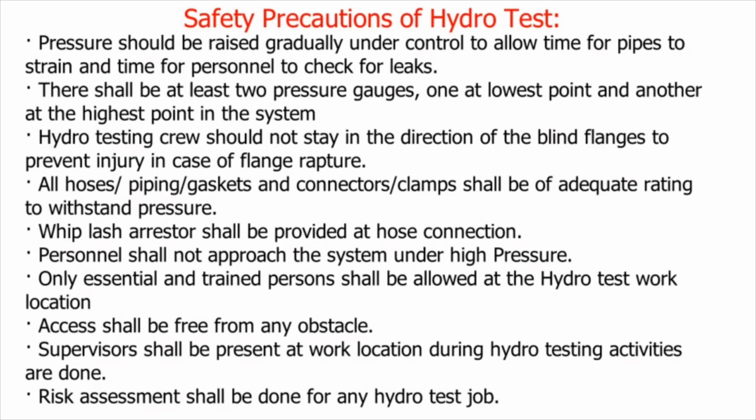All hoses/piping, gaskets and connectors, clamps shall be of adequate rating to withstand pressure. Whiplash arrestor shall be provided at hose connection. Personnel shall not approach the system under high pressure. Only essential and trained persons shall be allowed at the hydro test work location. Access shall be free from any obstacle.